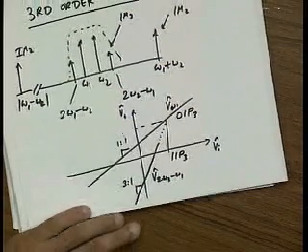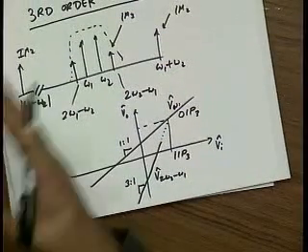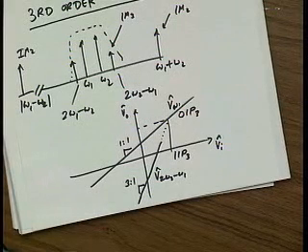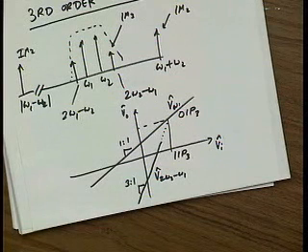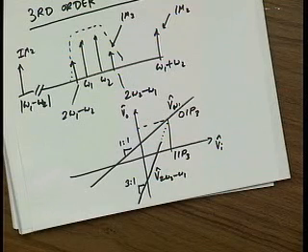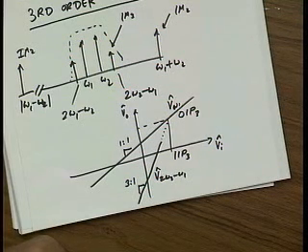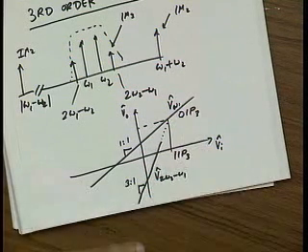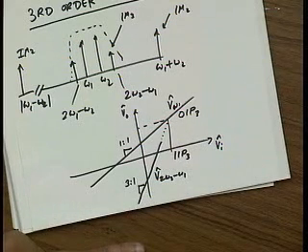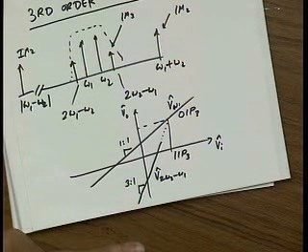And again, IP3 is the way you typically specify. If you go look at a data sheet for an amplifier, they're not going to tell you what IM3 is at some power level. What they will tell you is the IP3 point. And from the IP3 point, you can calculate basically where you can operate your amplifier. How much distortion can you tolerate? Well, let's say the IP3 point arbitrarily is at 0 dBm. Let's say you need 100 dB of IM3. What's the maximum input power that you can put in?